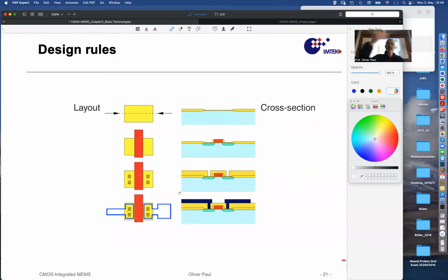Because all we have seen is now cut through a mask and what it does to the subjacent layers that are being etched. So in this low-cost process, we have elaborated structures like this that are separated by field oxides to either side, and then either thin oxide or something else small in between. And this field is, of course, viewed from top, some rectangular structure. So the mask that is imprinted, so to speak, onto the wafer is a 2D structure that has this shape, could have this shape of a rectangle.